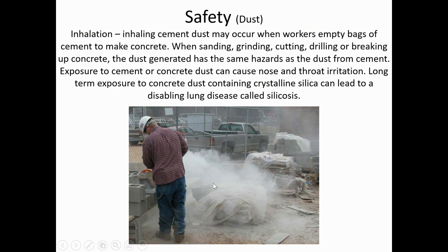All right, more safety with concrete. The cement is a really super fine dust, and it's really light. It just floats all over the place, and this dust is definitely not good to breathe.